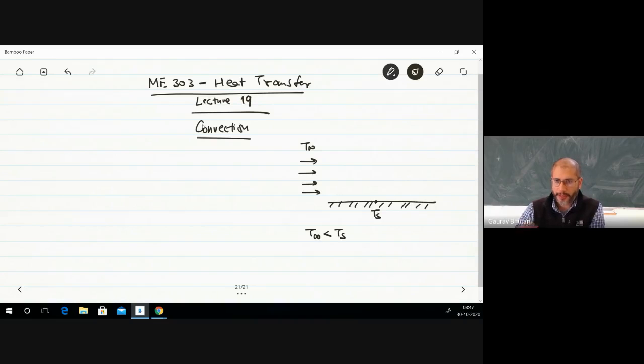Since we already know fluid mechanics, the no slip condition, assuming that condition is valid here, on the surface the fluid velocity is 0. So in this two-dimensional situation, on the surface we have u equal to 0 and v equal to 0. The fluid molecules touching the plate's surface are at 0 velocity. As you move up, the velocity profile develops, and then finally you have a boundary layer beyond which u is equal to u infinity.